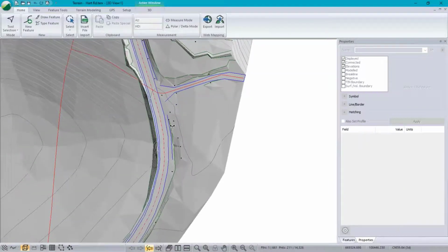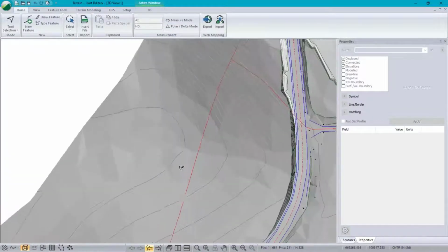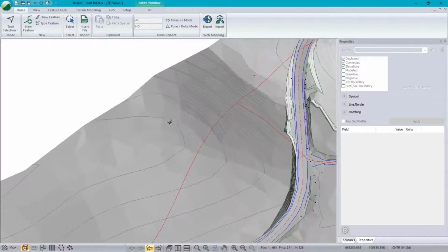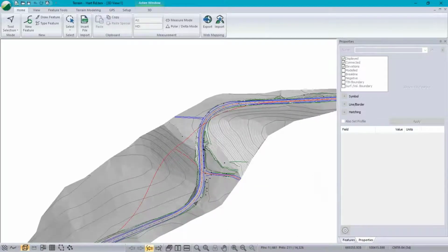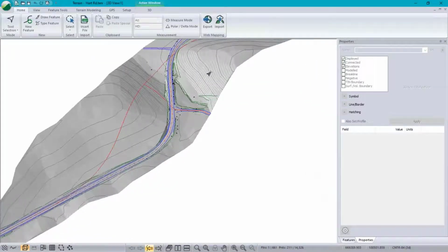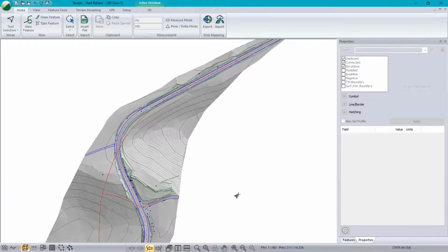If you click and drag, it always rotates about the last place you clicked on. So if I click on the top of the screen here and drag, there's the top of the hill. Sorry, not screen. Right. So track mouse helps you navigate because whenever you click on the surface and drag the left mouse to rotate, it rotates about the point you clicked on and it's in the center of the screen. This can be really useful for a long skinny road. I'll show you that in a sec.